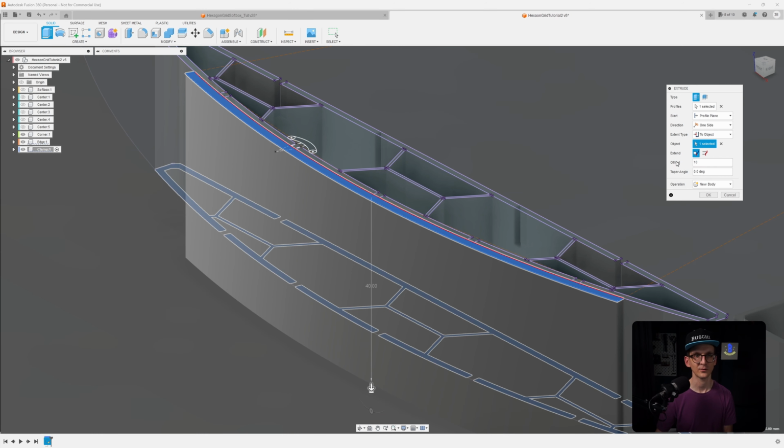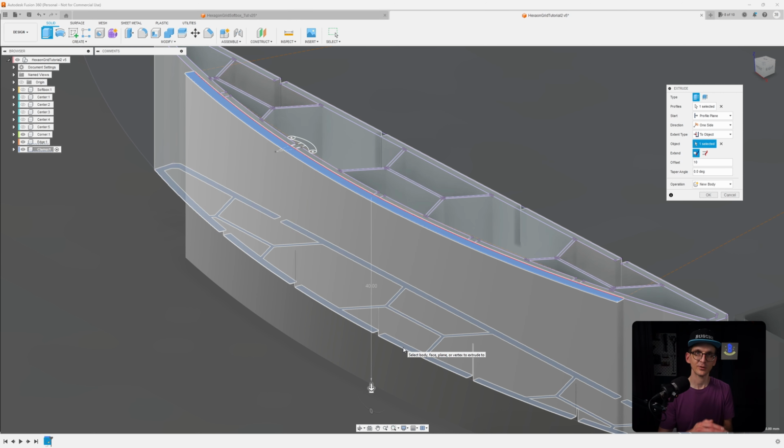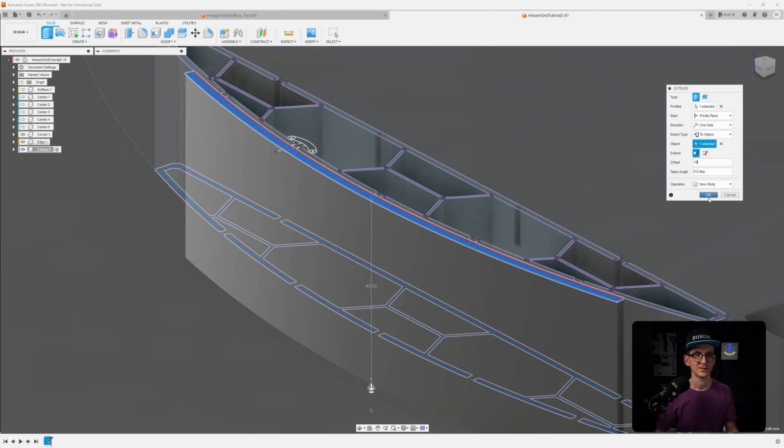I can do this with the offset, which is really nice. So I'm referencing, if I'm now changing, for example, the depth, this offset will be the same. So even if the grid itself is thicker or deeper, the clamp will always grow with the grid itself and then still reach the backside of the softbox the same way as before. So that's fine.